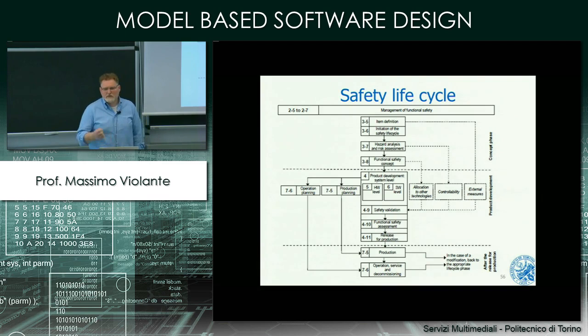So you see the whole engine, you see the whole vehicle. So there you specify the functionality. So you tell what you want to achieve. You analyze your system and you define the functional safety concepts. So what you want to achieve from your system in terms of nominal functionality and redundant functionality added there for functional safety.